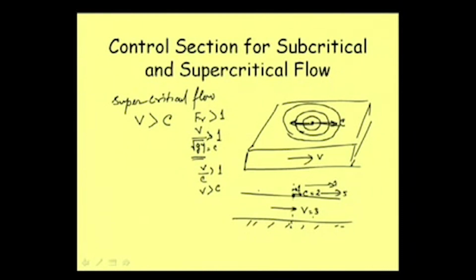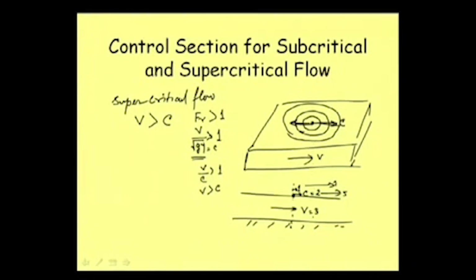In unsteady flow situations, when we will be discussing the characteristic equation, we will see that these characteristic curves are always in the positive direction in case of supercritical flow. Well, that part we are not discussing here. I am trying to explain this in terms of a very simple situation which is very familiar to us. And that's why the statement that we passed in the last class: in case of supercritical flow, any disturbance created at any section will not affect the upstream of the flow.